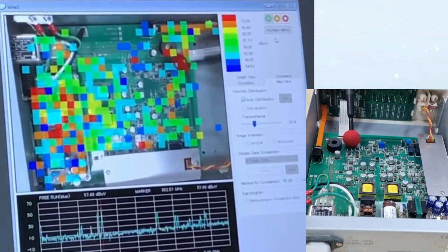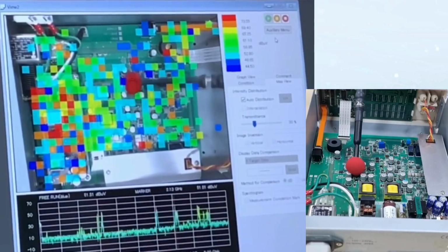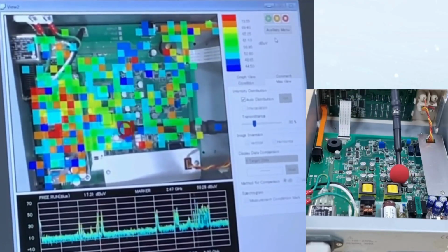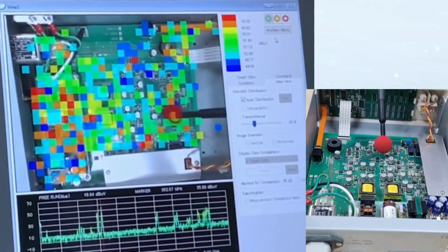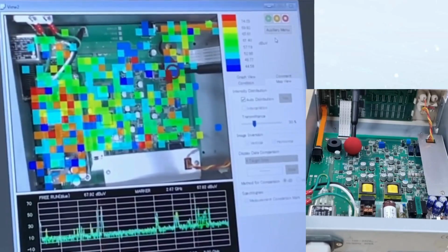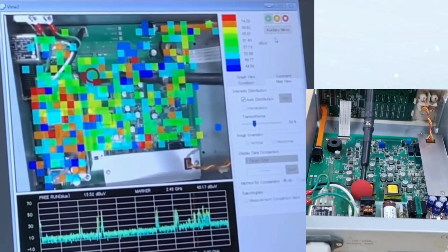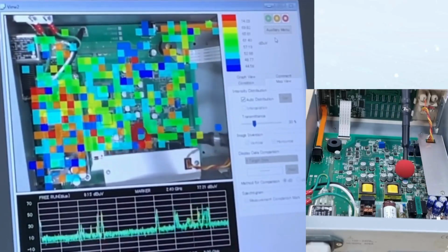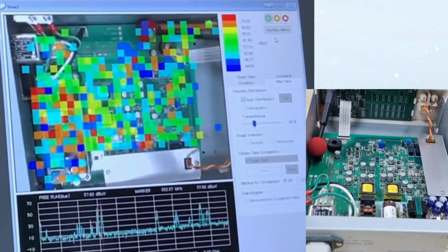You may want to do the scan using different probes. Different probes have different frequency characteristics. Some are suitable for low frequencies, and some are suitable for high frequencies. You may try using electrical probes and then magnetic probes to choose which is more appropriate for your noise condition.